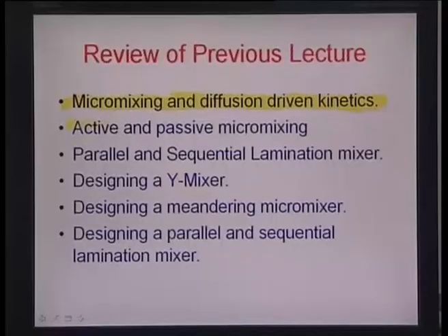We talked about active and passive micro mixers. Active mixers, if you may recall, are essentially those mixers where energy is being supplied externally by mechanical or non-mechanical means, and passive mixers are pure mixing by intelligent design, where you can split the flows apart many times and join them back so that they form laminae, and that way you reduce the interdiffusion length between the different mixing layers. Therefore the time of diffusion can be reduced in this manner and taken much below the residence time, so that there is mixing as long as the flows reside in the chip, and by the time it gets out they are totally mixed.